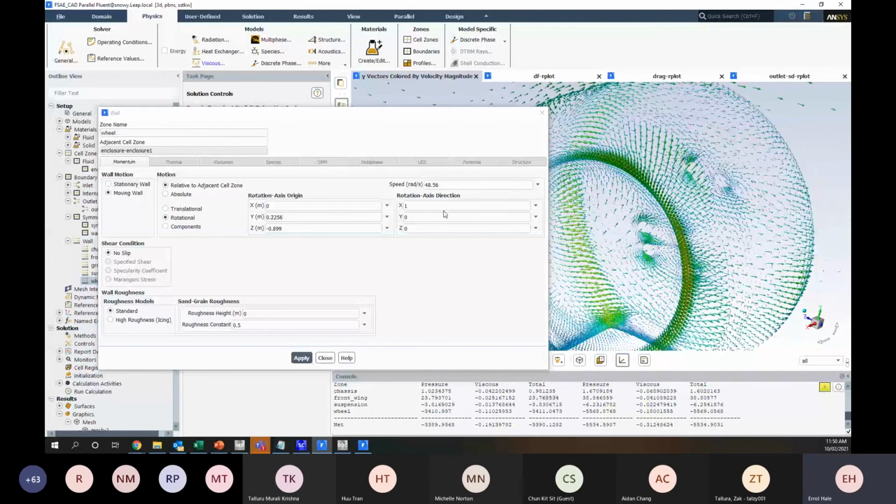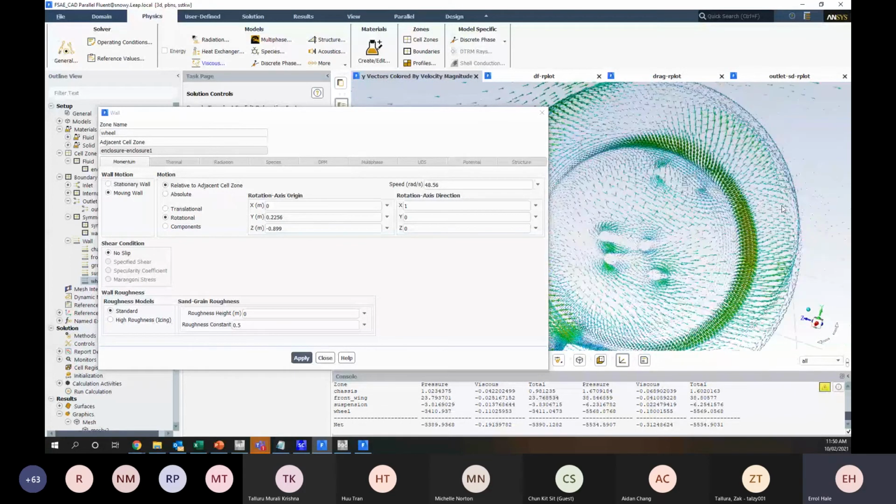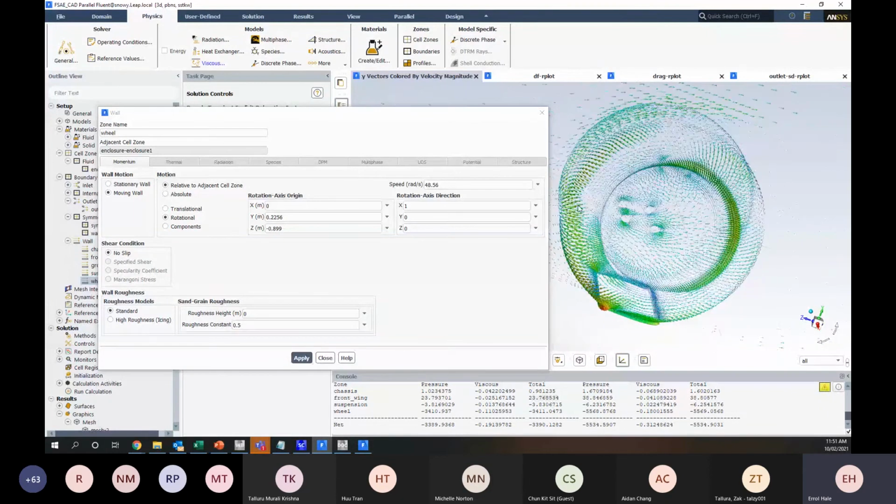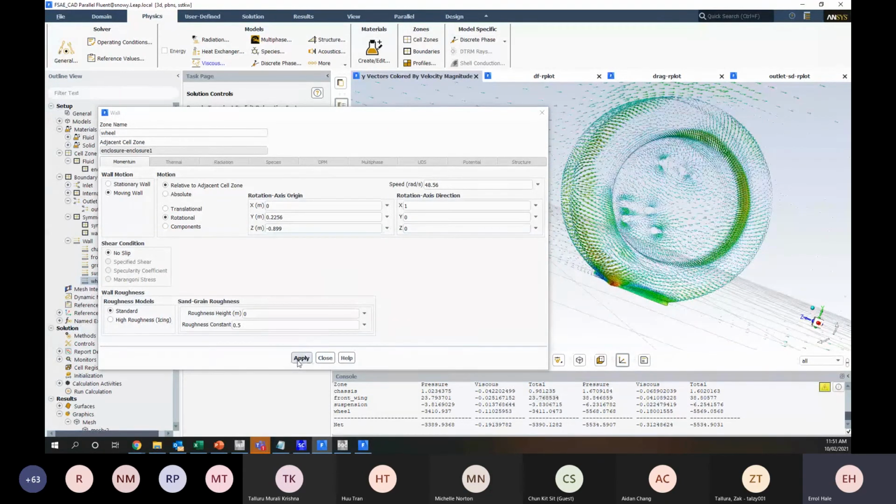I think it's definitely not rotating at the right speed, if anything, because it should be very clearly going this way. And the velocity at the surface should match that. So there's something I need to check. Maybe we'll check that for tomorrow, but it's good for us to be able to see this and figure out and show how to troubleshoot a simulation like this.